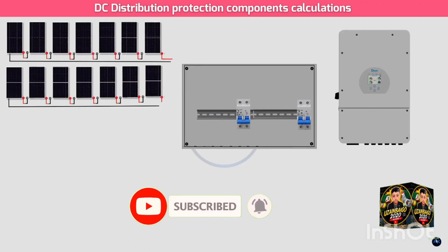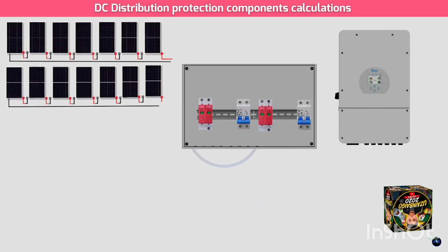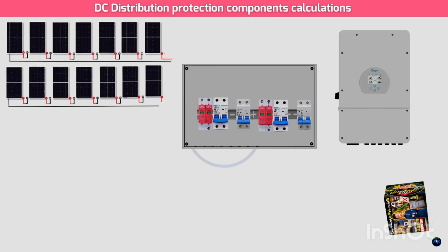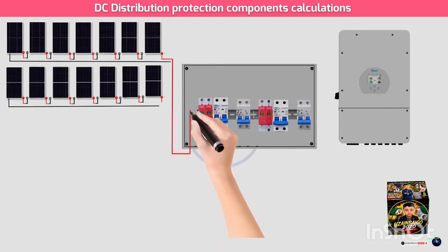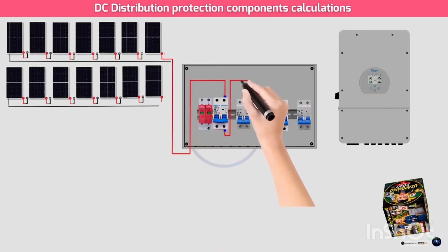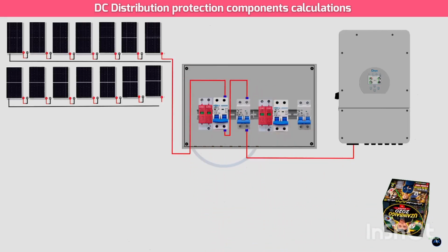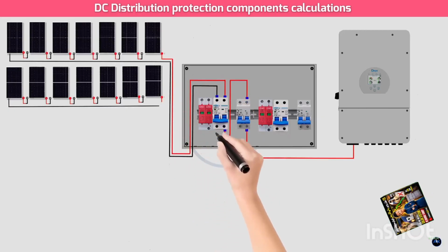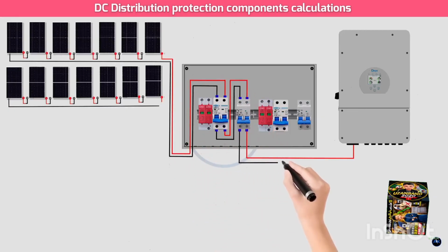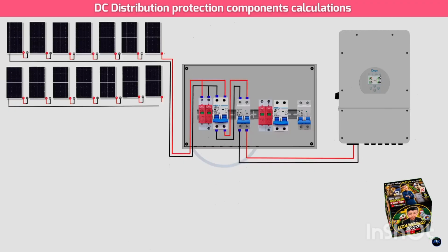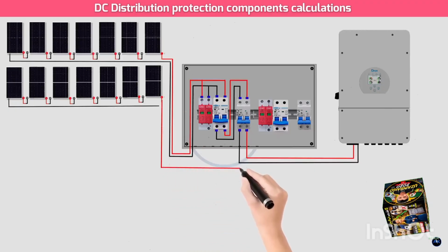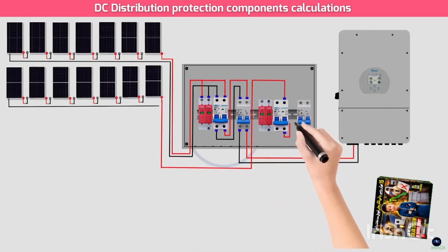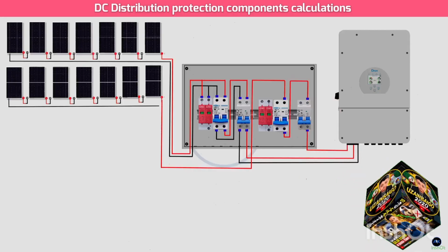This involves selecting the appropriate DC disconnect switch (DC isolator), DC surge protective device (DC SPD), and DC miniature circuit breaker (DCMCB). Again, I will use the hypothetical values established in the previous step. You must use the actual specifications from your solar panels and inverter, as well as the chosen DC components for your project. Let's assume a setup where each string has its own MCB and SPD, and then a main DC isolator before the inverter, or individual isolators per string if preferred.